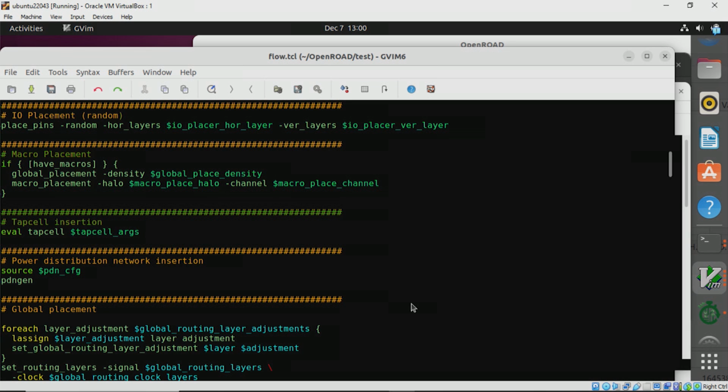The power distribution or the supply line should be placed first before doing any kind of placement. Then the tool will know that certain metals are in certain locations. Based on that, it will place the standard cells, then do the global and detailed routing, because the power is the most important part. So, that is done first.